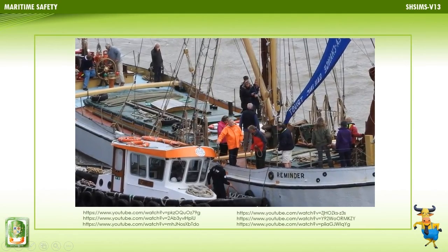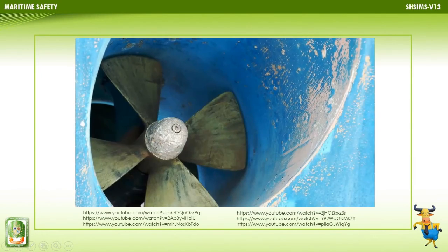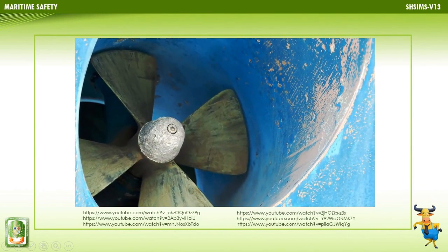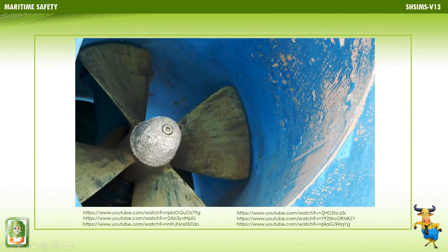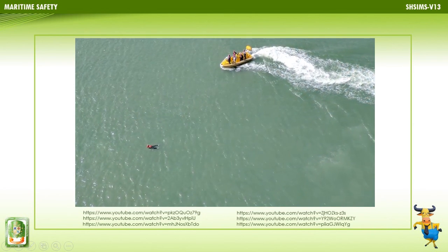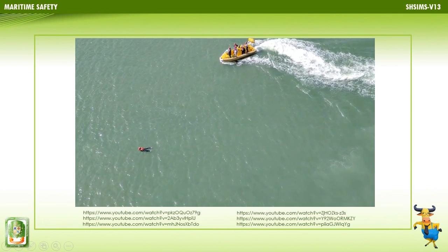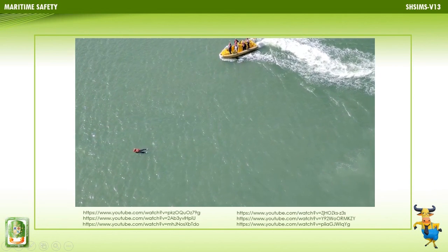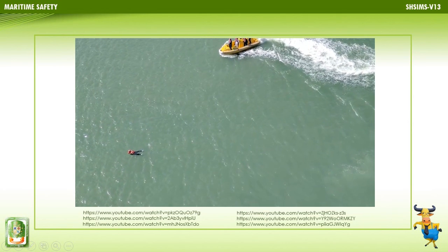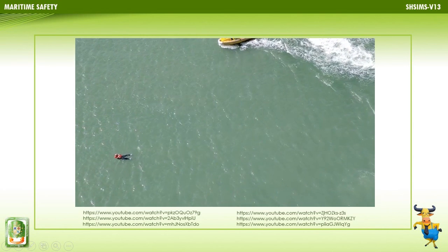There are different methods that can be employed to turn the CRV back towards the man overboard. Regardless of which method is employed, one thing that the crew member on the helm must be able to establish is the reciprocal course. The reciprocal of any course is found by adding or subtracting 180 degrees. For courses less than 180 degrees, add 180 degrees. For courses more than 180 degrees, subtract 180 degrees.